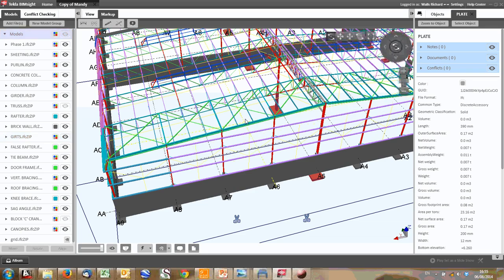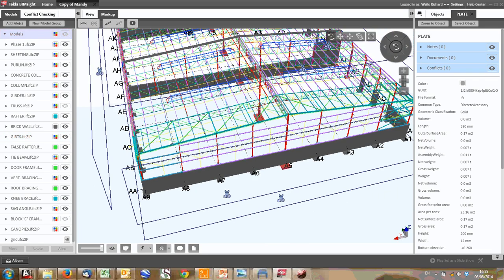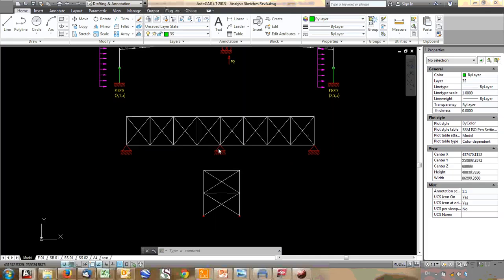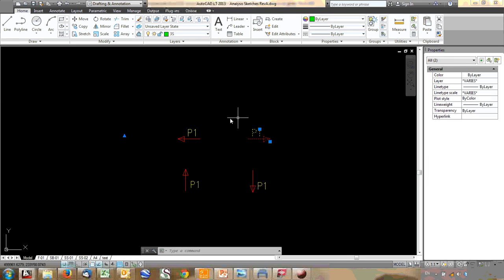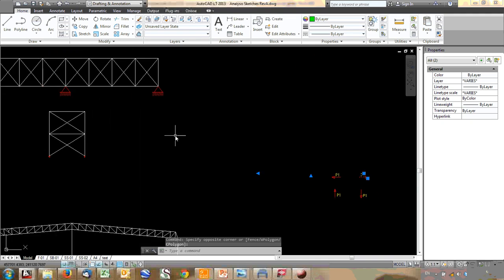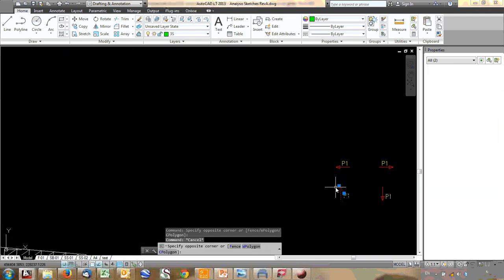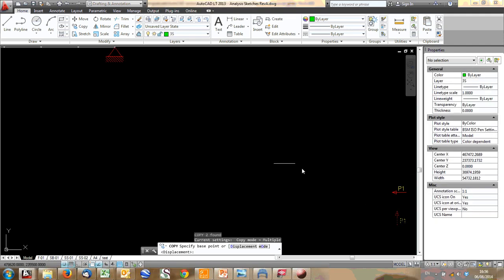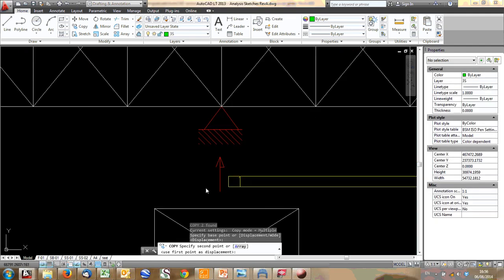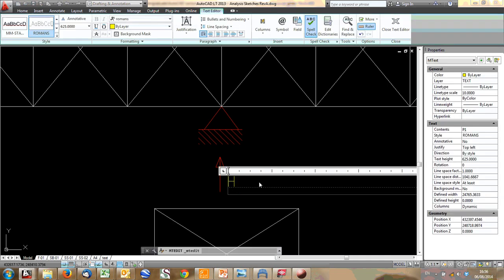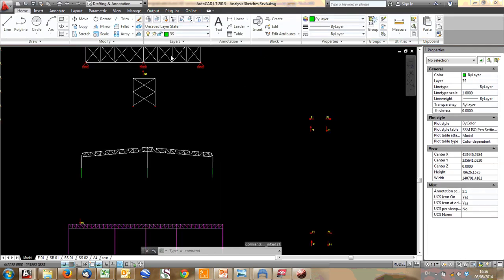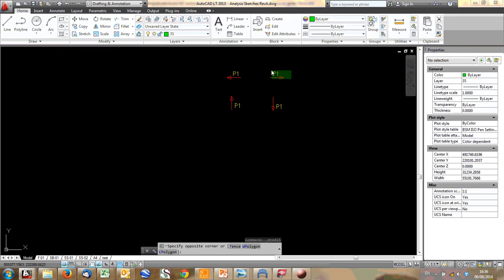We can quickly calculate our loads and then design for it. We can design this all the way along, and we'll get a reaction. From this, we get a reaction, which we then can apply to our girder. So there we go. Let's call this D5 or something. Our reaction here, and this is our girder load. Now it's a horizontal load, and this we now add to our girder.